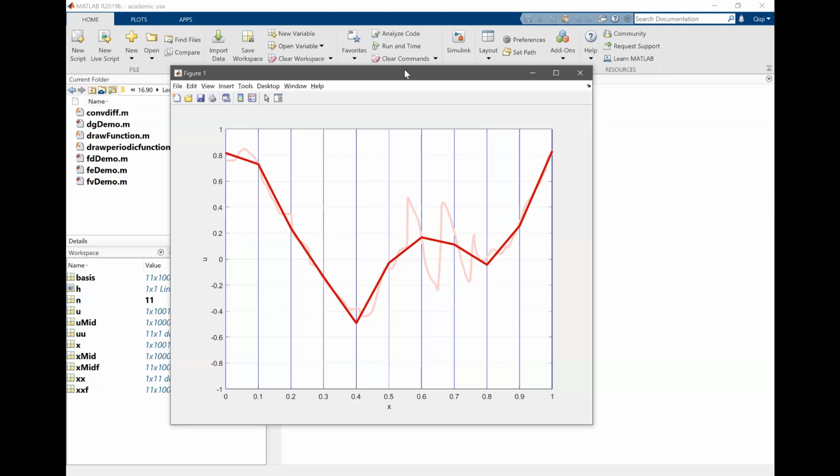In finite elements, we are approximating a function with another function. As you have pointed out, the function we use to approximate is not as general as any function. It is piecewise linear, it is continuous. So there is a lot of constraints on what kind of function I can use to do this approximation. But we still end up with a function. We are not just removing the concept of function and approximating it with a bunch of numbers, be it the value of the function at the grid points or the average of the functions. We still have a function to play with. So that's really an important difference between the other two methods and finite elements.